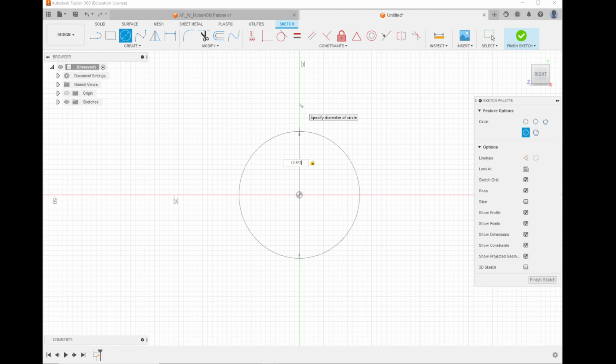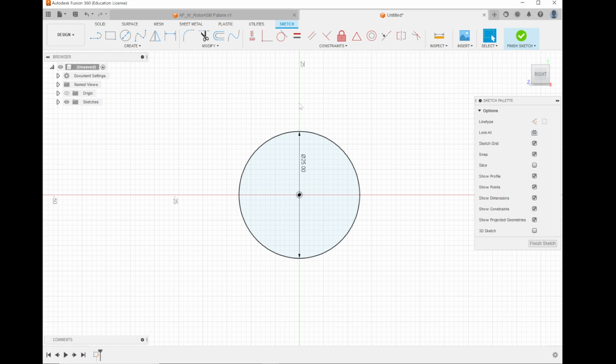So that's good for finding things like midpoints. You can also define specific lengths to do it algebraically. You can get a length on another part of your design and define it as length D, and then in another sketch you can say this is 1.5D in its size. Press enter when you've done that.